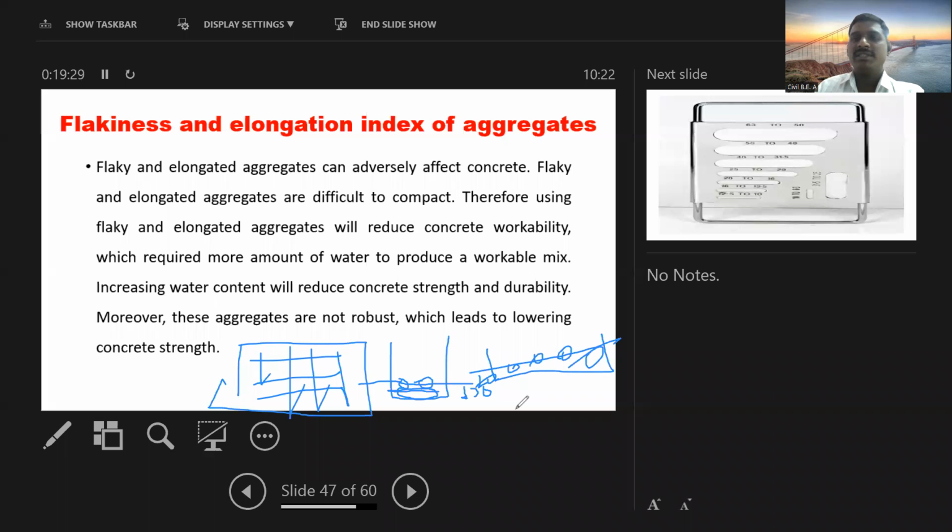So the aggregate should pass below that particular rod. Whatever bars we have placed in the X and Y directions in the slab, the aggregate should pass below them. So this aggregate size should be 20 mm.